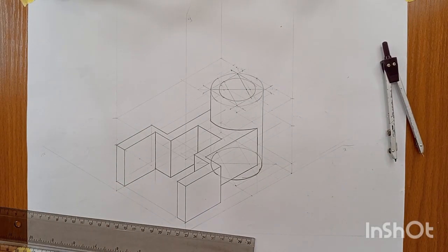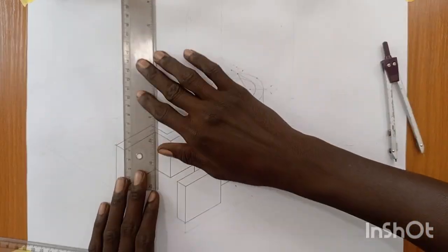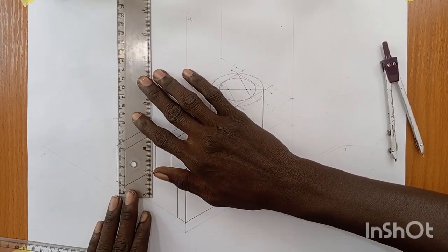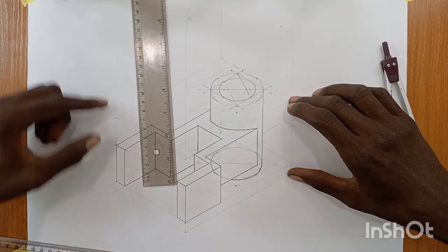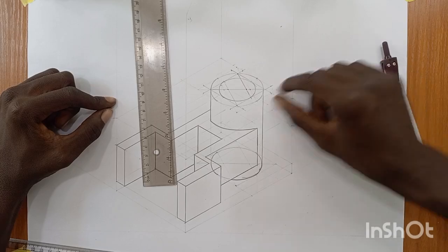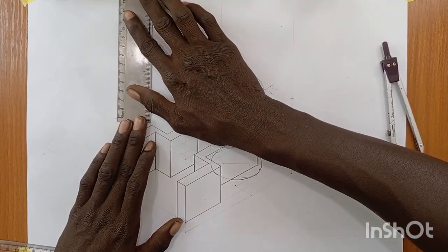So now to draw the top of the smaller cylinder, as we said earlier, the bigger cylinder is 80 mm and the total height of our drawing is 96 mm. So now I'm going to add 16 from here. Here to here is 80. So I'll add 16 here, 16 here, 16 here, and also 16 here. So let's do so. I'll measure 16.